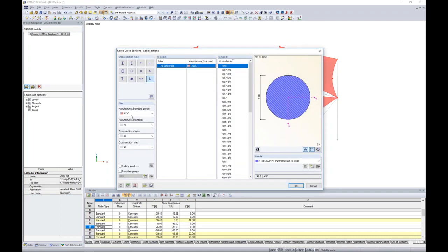sections. So this just has some pre-populated diameters. They're basically just round bars populated from the AISC with set diameters, but you can always create your own with a parametric section. We'll choose a 1/2 inch diameter cable. The material is also set within this same dialog box.